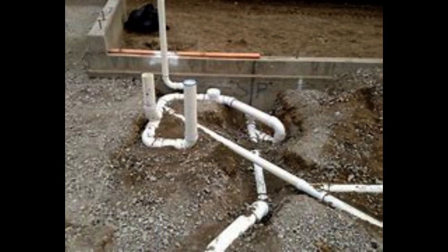5. If applicable, the absence of a pan or a pan drain system that does not terminate over a waste receptor or to the exterior of the building above the ground surface. 6. Inappropriate locations. 7. The lack of protection from physical damage. 8. Burners, burner ignition devices or heating elements, switches, or thermostats that are not a minimum of 18 inches above the lowest garage floor elevation, unless the unit is listed for garage floor installation. 9.